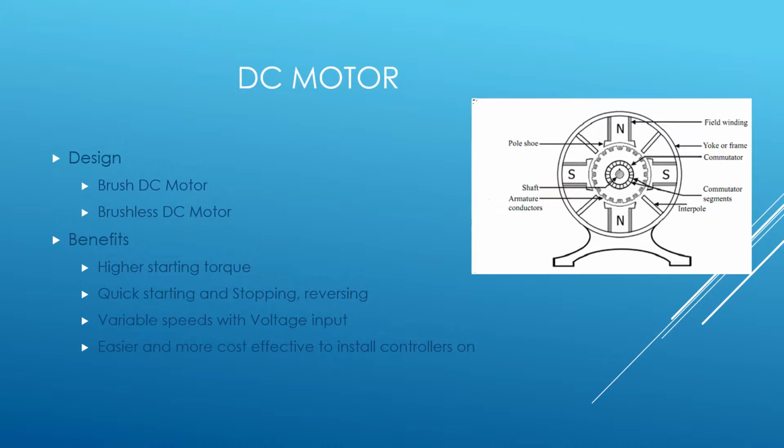A brushless motor, by contrast, uses a permanent magnet as external rotor. In addition, it uses three phases of driving coils and a specialized sensor that tracks rotor position. As the sensor tracks the rotor position, it sends out reference signals to the controller. The controller in turn activates the coils in the structure, one phase after the other.